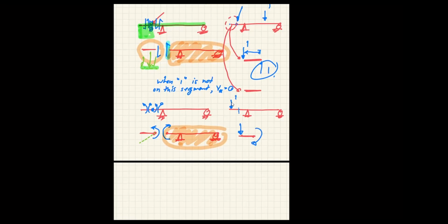Okay. But when the load moves away from point A, moves past point A, let's say it's here, would it be able to bend point A? Or when it moves here, what will happen to point A? Nothing, right? The load moves away, and especially when it reaches the internal span, the overhanging portion is meaningless now because the load is here. So you have just a simple beam.